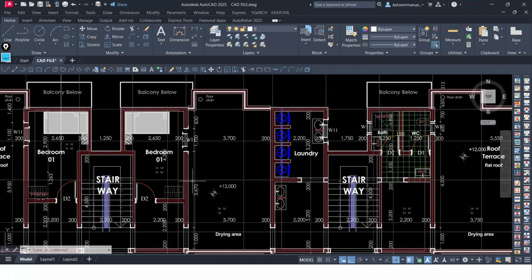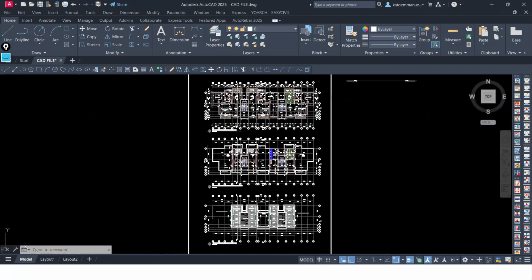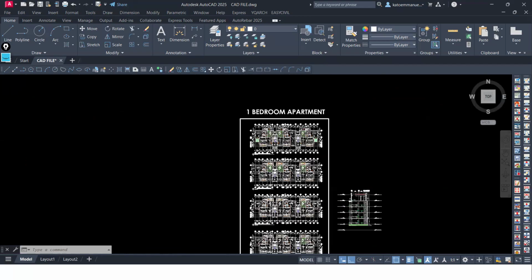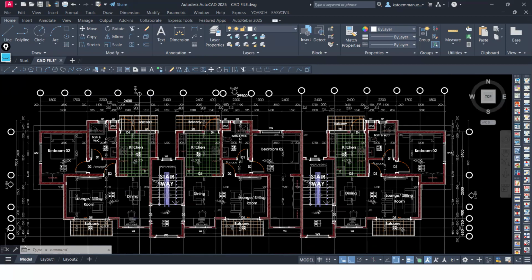If the building has some parts that are, maybe, dancing halls, in those areas you're going to experience a lot of vibrations. Ribbed slabs are not good at sustaining excessive vibrations. So you can consider adding solid slabs in those partitions. Yes. After identifying that, now you come and make a scheme of your structural elements using the first floor plan.